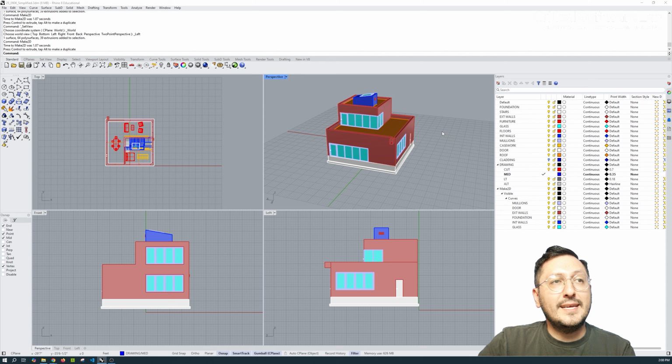We use a clipping plane instead. And a clipping plane is another type of plane that allows us to automatically hide parts of the model so that we can look inside of it. This is going to be key for us to produce plans and sections, the two types of orthographic drawings that rely on a cut through an object.